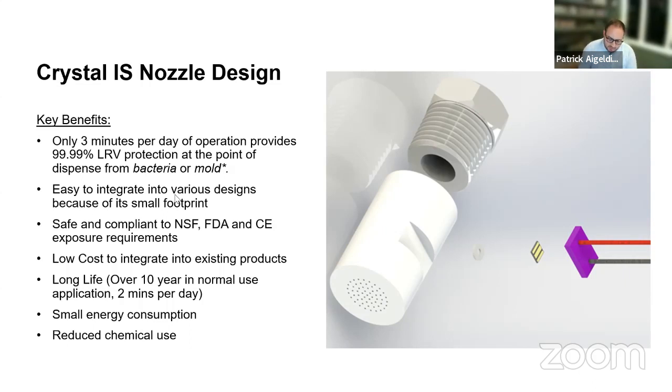But just for clarity, the water is only getting treated very slightly because of the flow path. Once you get above a liter per minute, you're only getting a small amount of the UV dose into the water. So the goal would be that you would treat the water with a different UV device, possibly at point of entry or farther up in the system, maybe all the way back into the municipal system.